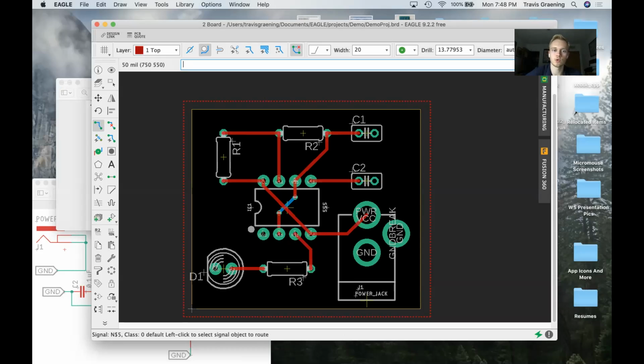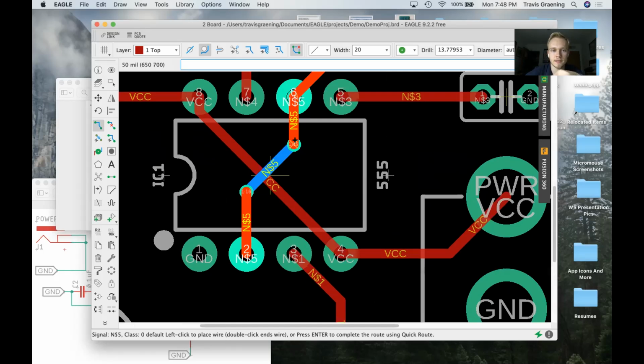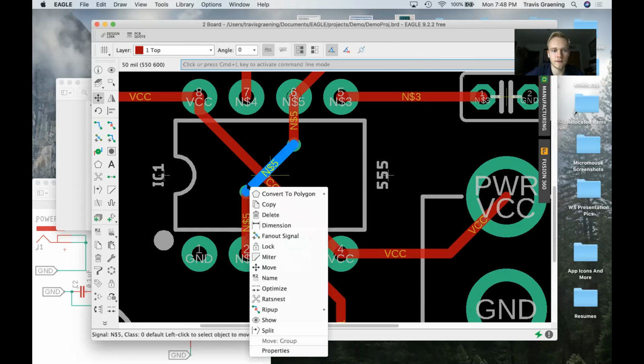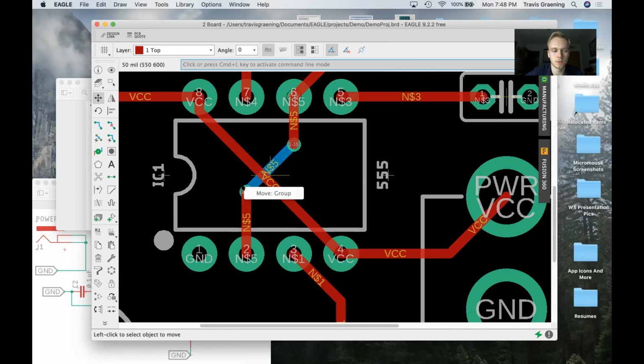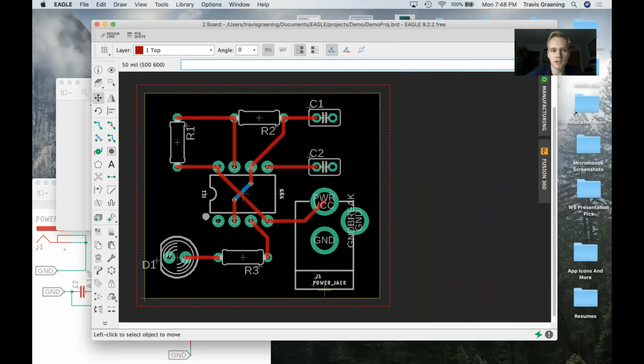And there you go, you made your connection. So this is a really useful tool. But once again, if you have a really fidgety analog trace, you're not going to want to use too many vias because it can just mess with your signal a little bit. And there's also for the vias, if you zoom in, there's also sizes and stuff that you can adjust about them, and it can be a little bit fidgety to actually click on them, but we can worry about that at another time. So yeah, we've made our finalized PCB right now.